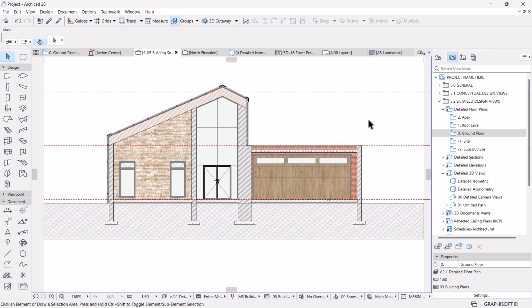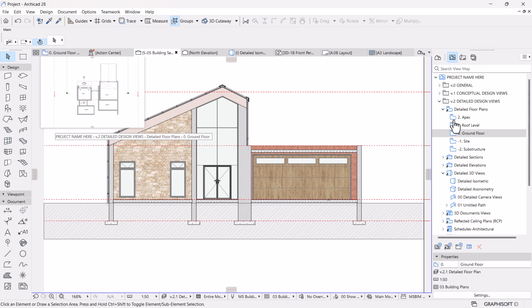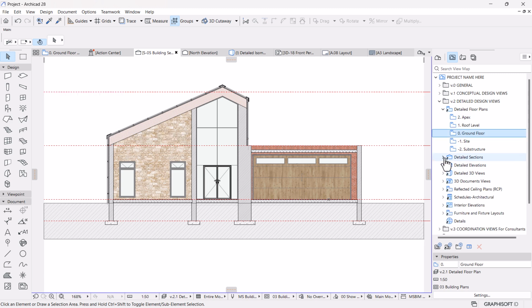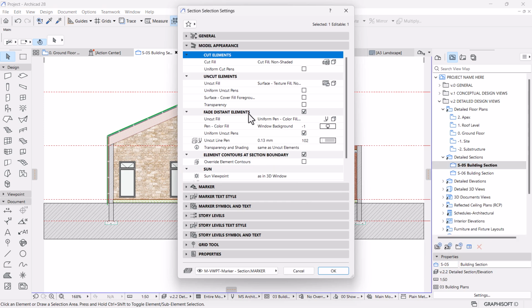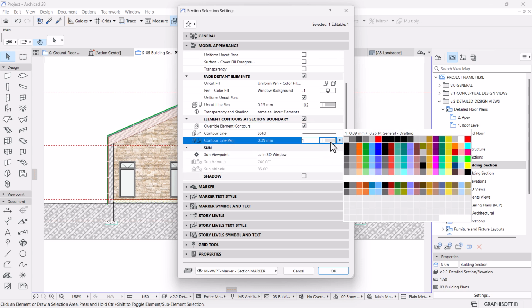You can modify a bit, like maybe introduce shadows, or let's do that. I'm going to introduce shadows. I'm going to do it right here on the view under detail section. I think it should be section 1, right? Yes. I want it to have override. But anyway, let's right click and go to section settings. What I want is under the model view appearance, let's set the shadow active, and then I'm going to set them to be color.